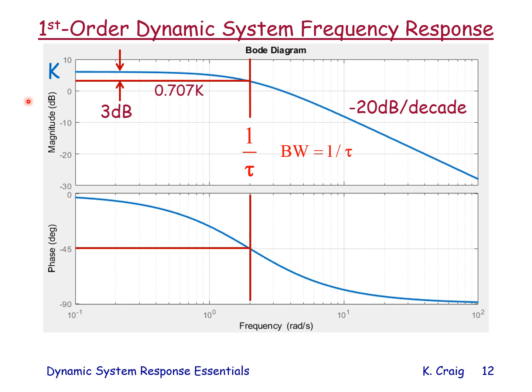So I see here that if I were to plot the frequency response for my first order system, in the beginning it's flat with an amplitude ratio of K, output over input. At a frequency of 1 over tau, the amplitude drops minus 3 dB, or 0.707 of the low frequency value.